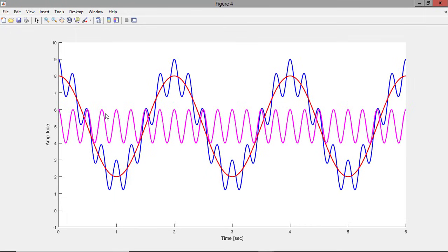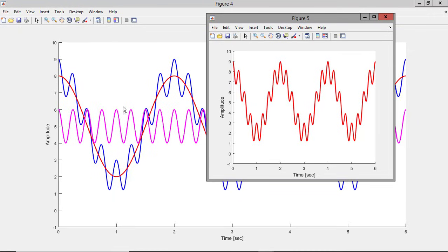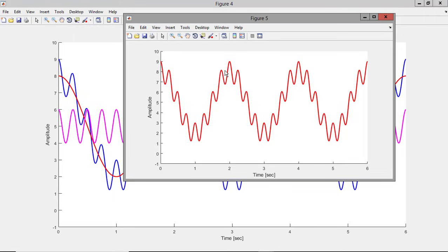And you'll notice all the peaks line up, right? The peaks from the magenta and the blue curves here. And so I need to look in terms of a Fourier series at the addition, at every moment of time, of the red and magenta curves, and that will give me the resulting curve here. So if I add this fundamental frequency at 1/2 hertz to this 4 hertz higher frequency component, I'll end up with the following plot here, where now the red curve is the summation of the two, the Fourier series of the two, and it's landing right on top of the original blue signal.